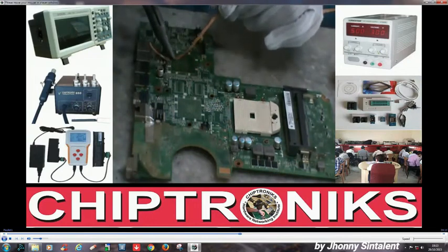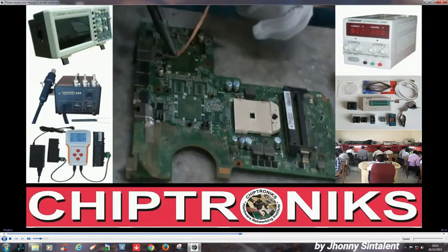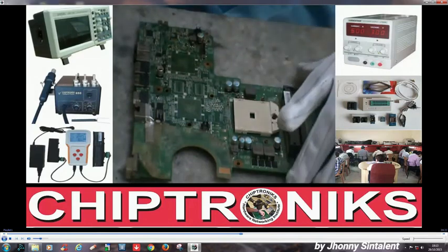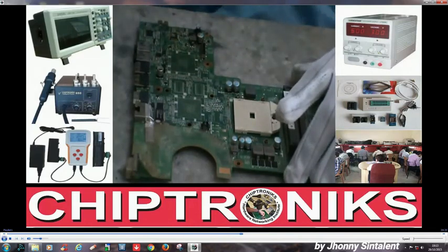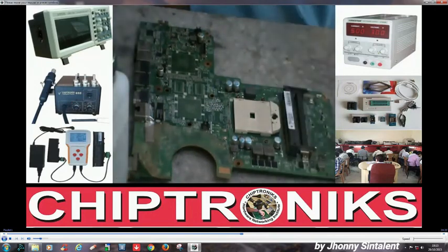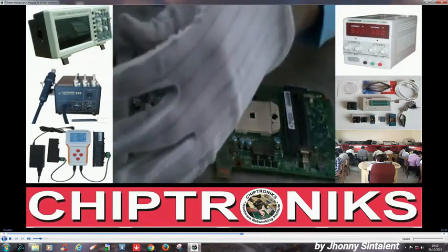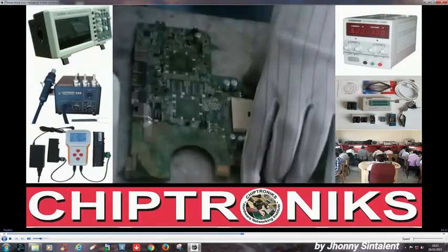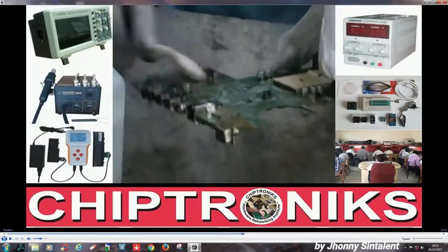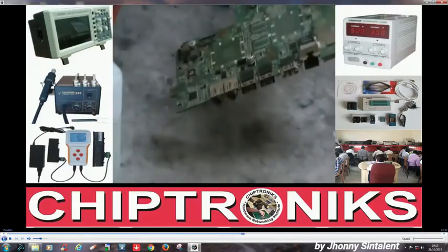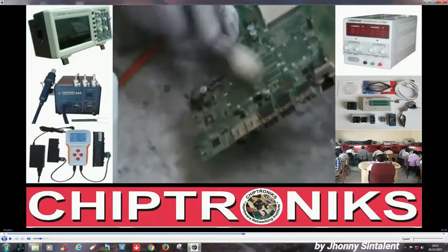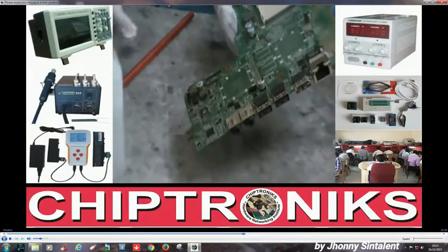You can see we have cleaned all the BGA pads, and now we'll remove the residue through a brush using thinner. You can see we are using thinner to clean this. Yes, we wash the pads with thinner this way. Yes, it has to be done firmly, like this.